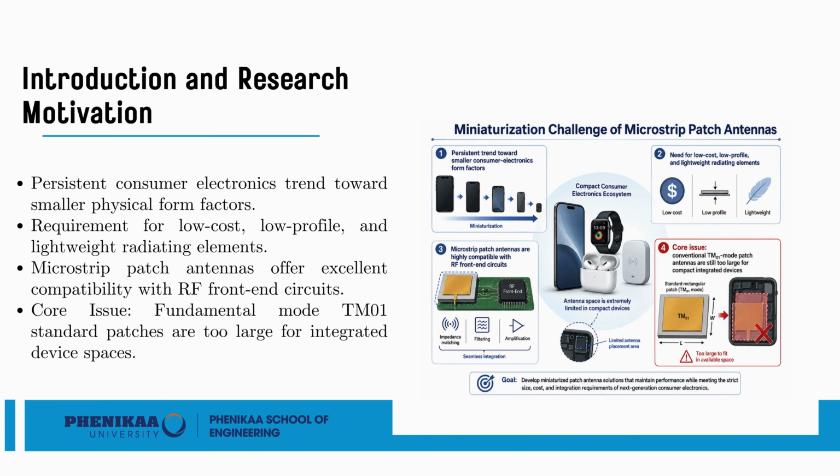Microstrip patch antennas remain highly favored for these architectures because they present a low profile, are lightweight, and support simple, direct fabrication onto planar radio frequency front-end circuit boards. However, when a standard patch antenna operates at its fundamental TM10 mode, its resonant length is determined by a half-wavelength requirement, making the physical dimensions far too large for modern space-constrained devices.